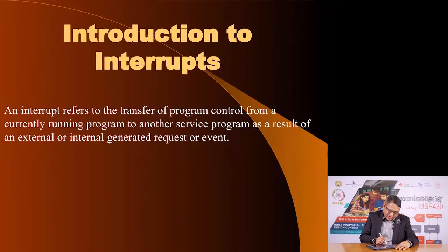Now, this event could be because of an external event, meaning somebody has pressed a switch, or because of an internally generated request or event. For example, maybe the microcontroller has an ADC, an analog to digital converter. An analog to digital converter takes a long time to complete a conversion, and after the conversion is over, the ADC peripheral could generate an interrupt telling the microcontroller that the conversion is over, kindly look at the result and do whatever you have to do. So, interrupts could be generated from external sources as well as internal peripherals.